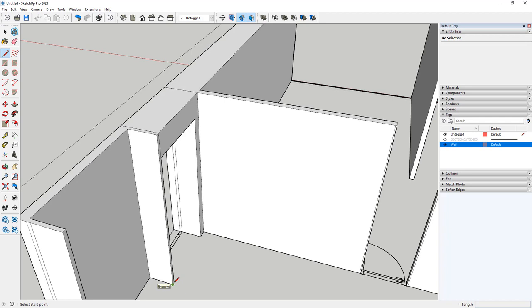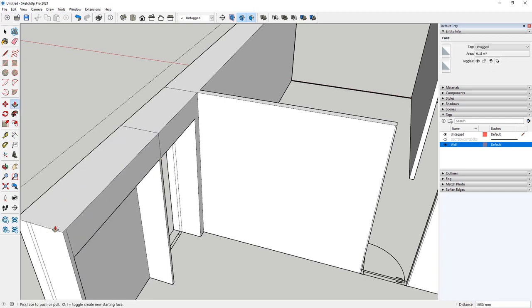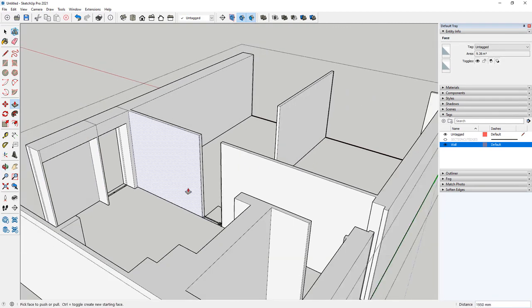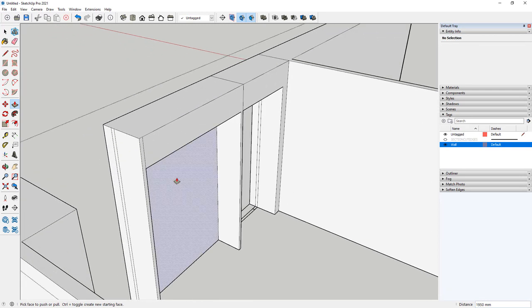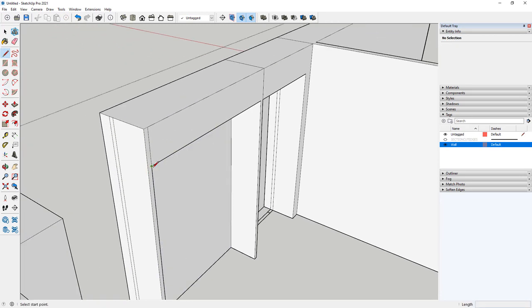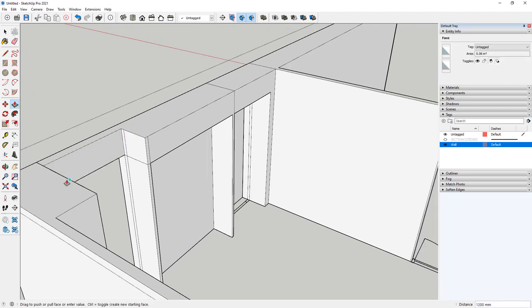So we go back to the pencil. Then we need to set 2600 again. Now we need to put the line horizontal and make just push pull. The same in the last area, so we can extend the existing line and use it as a reference to add push pull for the top.